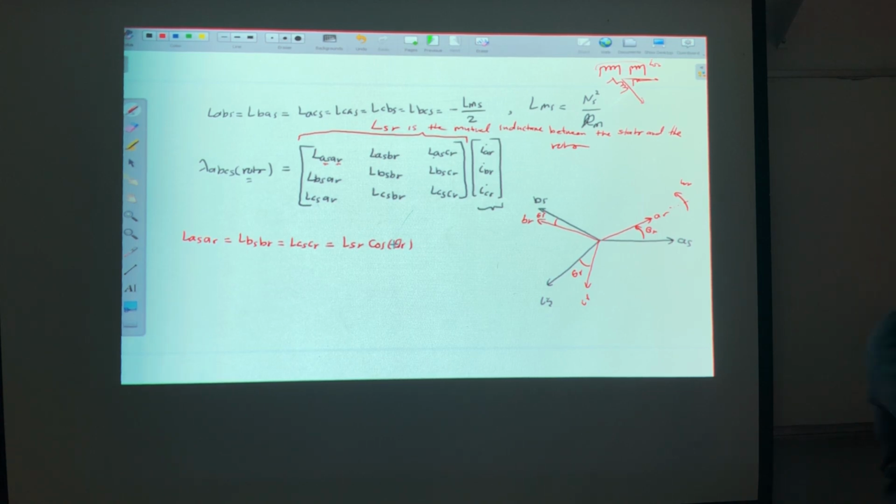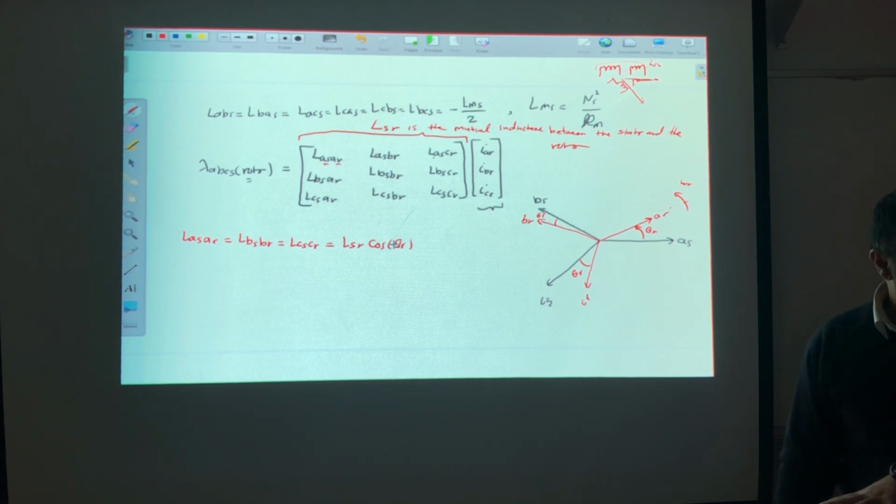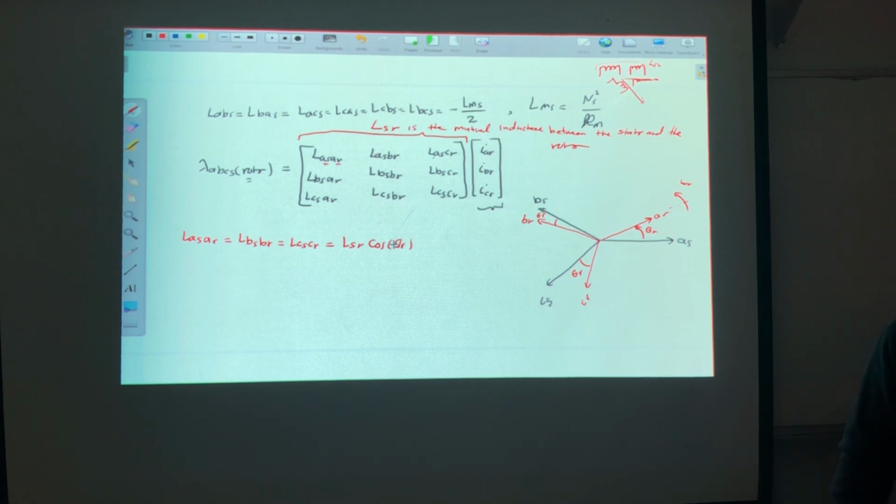In the view of volt per hertz control, why can we not reduce the frequency while the voltage is constant? Because the flux will increase. Someone said, yes, the flux is increasing. I'm happy because the torque will increase. You say, no. Why? Because at a certain point, the flux will never change, so you are consuming current that you never need. This will be dissipated as heat, as magnetizing current, as losses in the core. Core losses.